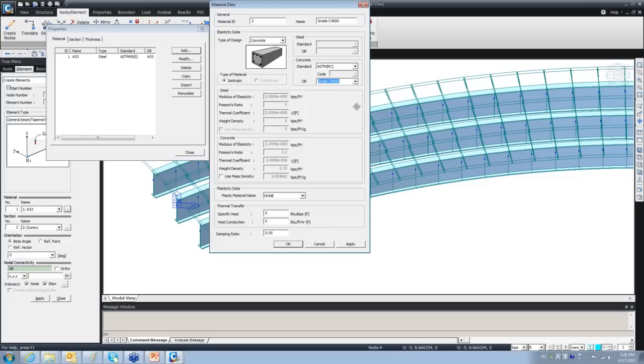stiffness as the deck. But here's the thing, we are using a dummy element, which means in real life we are not seeing those, and we are just using them for the sake of modeling to make these transverse connections and ensure the girders are working together. So we are just interested in the stiffness, not the self-weight itself. Okay, so somehow we have to change the self-weight and make it 0. So I select none, and then turn the self-weight density to 0.